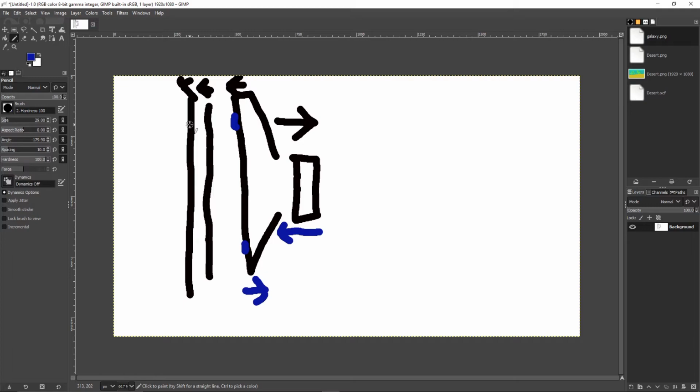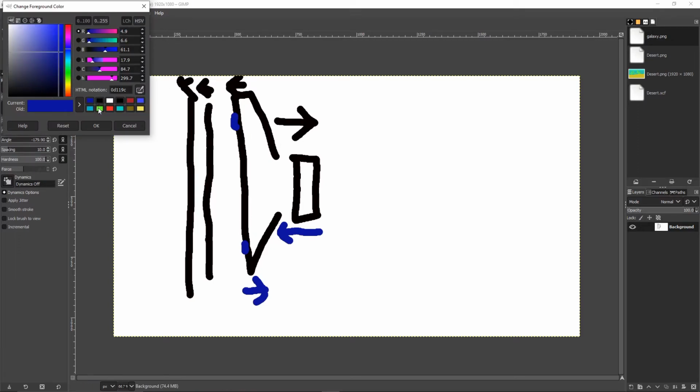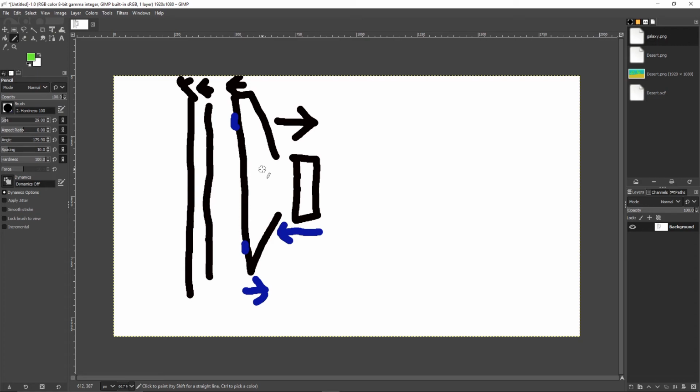Then, so your foot is all the way down, right? We're pushing this throw-out bearing into the pressure plate. It's disengaging the clutch. You shift gears or you do whatever, and we're ready to re-engage the clutch. So you bring your foot up. These springs, let's change colors one more time. Try green. So now we're going backwards. The springs push back. That's why the clutch pedal comes back up by itself. The springs push the bearing back.